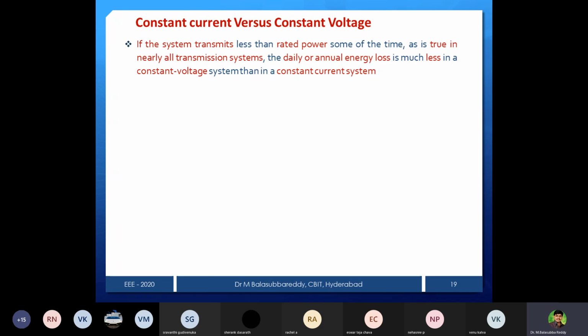You can use series compensators in that particular line to reduce its impedance, so that it allows more power to be transmitted on that line. If the impedance offered by that line is less, then automatically the losses in that line are also minimized. That way we are able to reschedule the power. That is the optimal power flow. In power systems we study load flows, but in later subjects we get it as optimal power flow.